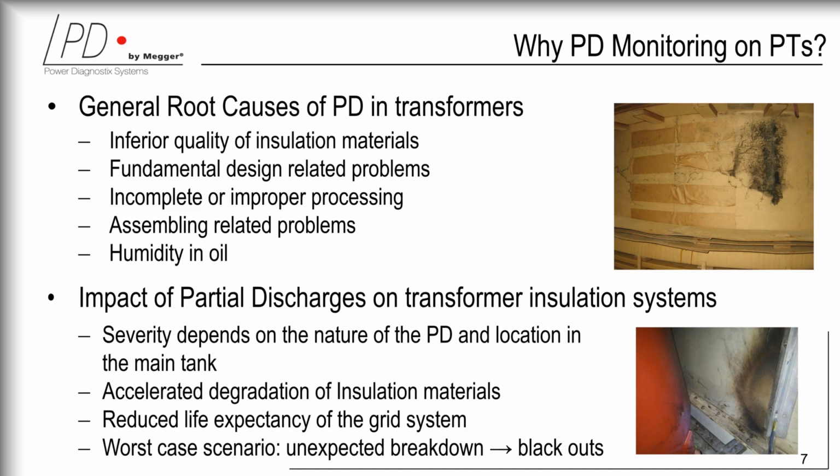The usual phenomena, as you know, is that problems with the insulation, particularly with paper, generate certain gases, and these gases are effectively explosive gases, acetylene, methane, and so on, and those can cause significant issues. The impact of partial discharge on transformer insulation can have a different level of severity. In fact, during the acceptance testing, both factory and site, there are certain predefined limits for the partial discharge that can occur at different voltages for a certain amount of time, etc. All these are specified in IEC type norms, and that's how all transformer factories are testing their devices.